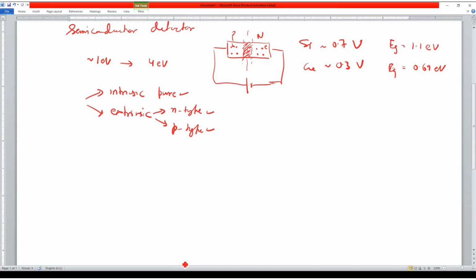Normally in an intrinsic semiconductor, let me write it here. In intrinsic, Ni is roughly equal to Pi, meaning the number of electrons will be equal to the number of holes, obviously, because the charge is generated either by some defect which is not concerned with the dopant, or by thermal generation, meaning some electrons have left a vacancy in the valence band and gone to the conduction band because they have got enough energy to cross.